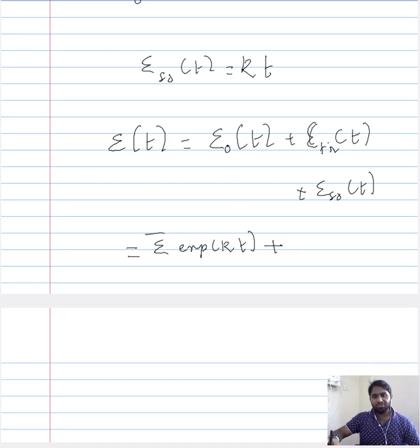The second region considers the transient region, which, as we have seen, we have categorized as stage 1 of the creep, and here there is a decelerating strain. It is expressed in this manner, wherein with time the amount of strain decreases, and the degree of decrease is encompassed by this prefactor beta.